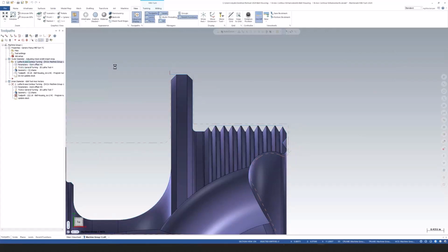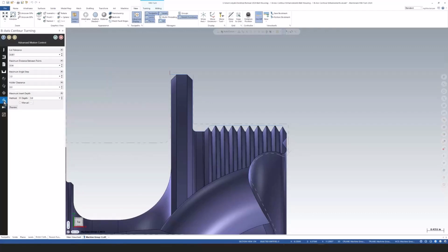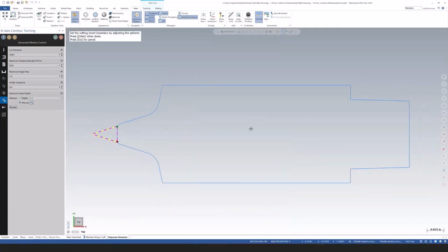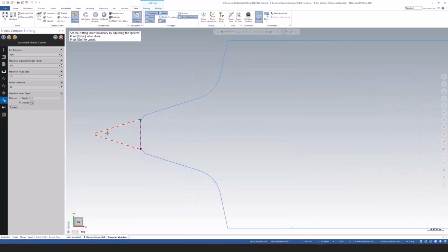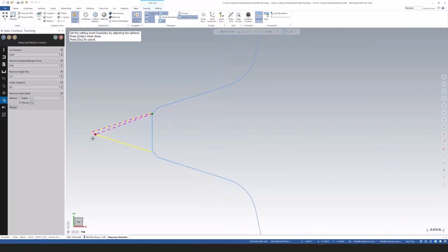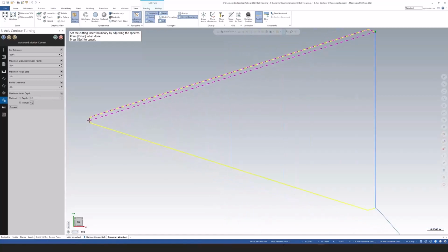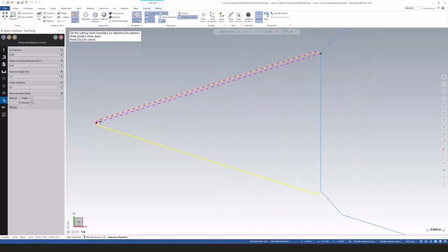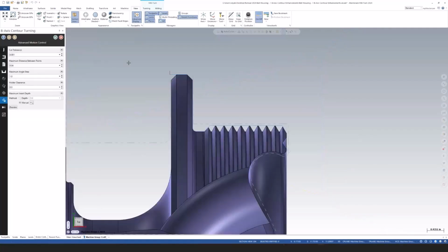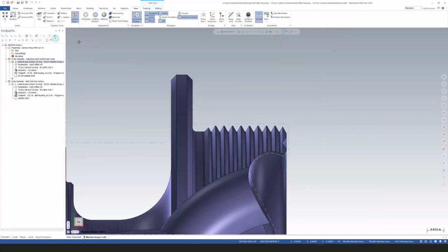Last thing I want to do is adjust where I can cut on the insert. Now, you can go in and say, hey, don't let the insert go past a certain depth. But I don't care about the depth. I just want to make sure it only cuts on the front edge. So you can now manually specify where on the cutter you are allowed to cut. Instead of saying, okay, don't go past this depth, just say don't cut on the backside, because this will basically completely eliminate plunging. This will say, hey, don't ever cut on the back end, rotate as needed to maintain cutting on the front face, which is where I'm intending this to be.